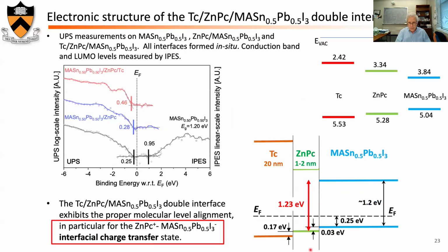One important thing, of course, is that when you deposit material on any semiconductor, and on perovskite in particular, you need to see whether the overlayer that you put on does shift the Fermi level in the energy gap of the perovskite, in which case then you need to readjust for your interface electronic structure.